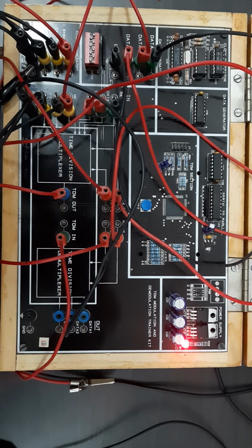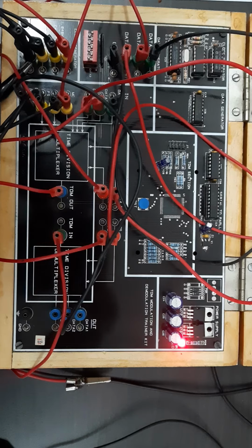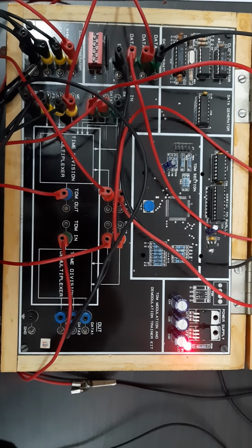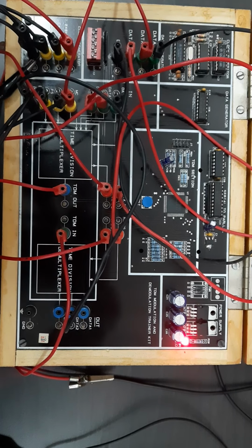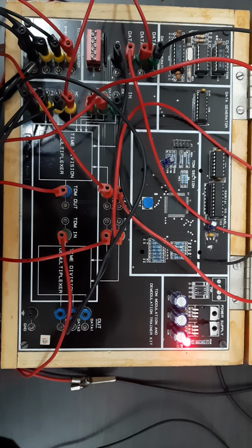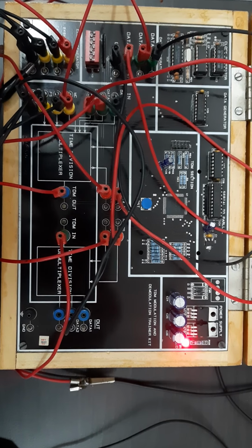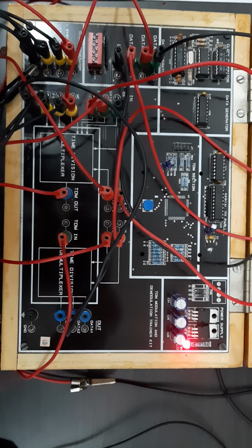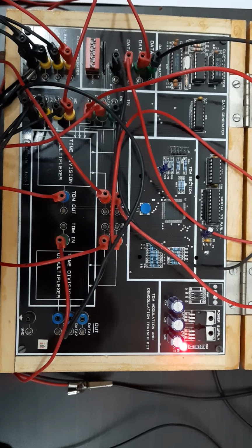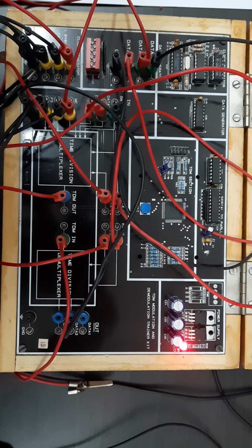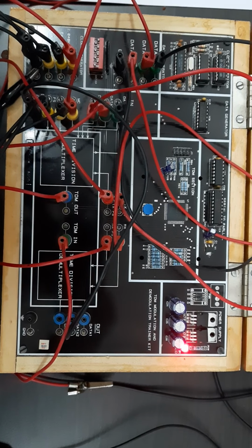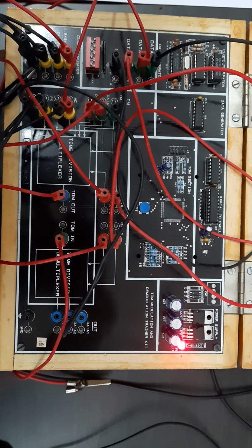Coming to the theoretical background of this experiment, the TDM system is highly sensitive to the dispersion in the common channel, that is the variation of the amplitude with the frequency or lack of proportionality of phase with the frequency. Accordingly, accurate equalization of both magnitude and phase response of the channel is necessary to ensure satisfactory operation of the system. Unlike FDM, TDM is immune to the non-linearities in the channel as a source of crosstalk.